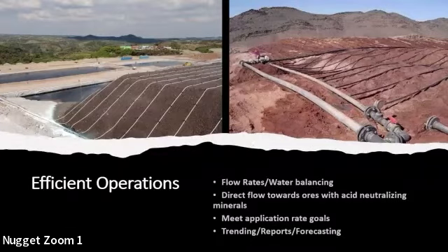Now they're processing material with lower ore grade, so there are a lot of other materials with different geotechnical properties being placed over the facility, with more argillic content. There were concerns about the potential development of a phreatic level, or clogs that could form.